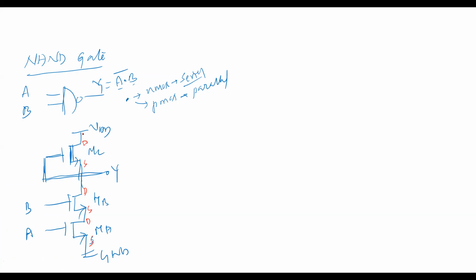Students, do you understand this one? Why are these two in series or parallel? These two transistors are in series. Why? It is already given here: dot means series in NMOS technology. Suppose it is a 3-input NAND gate, then A dot B dot C comes, and we have to connect 3 transistors in series. Anyhow, the stick diagram for this one is very easy.